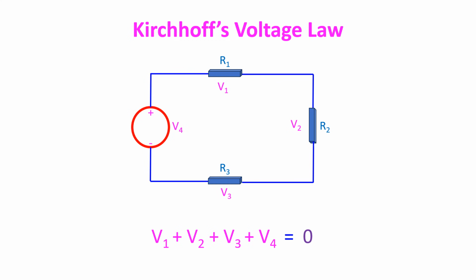Circuits having multiple loops can be analyzed by applying Kirchhoff's voltage law to each of the loops. Kirchhoff's voltage law follows the principle of conservation of energy. The loops can be traced in clockwise or counterclockwise direction. As the induced electric field produced by an inductor may not be confined to the inductor, leaked fields can cause error in calculation with high frequency alternating current circuits.